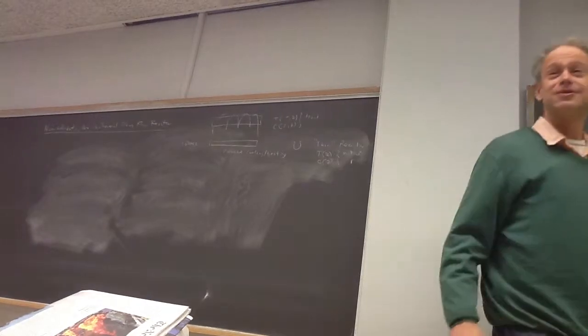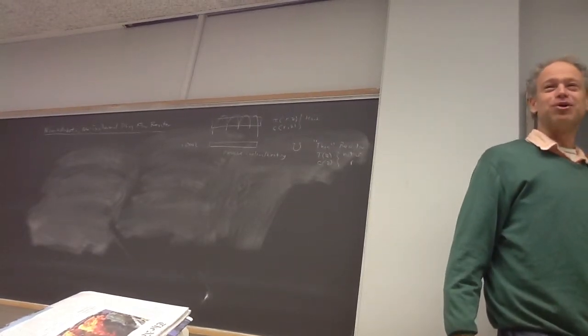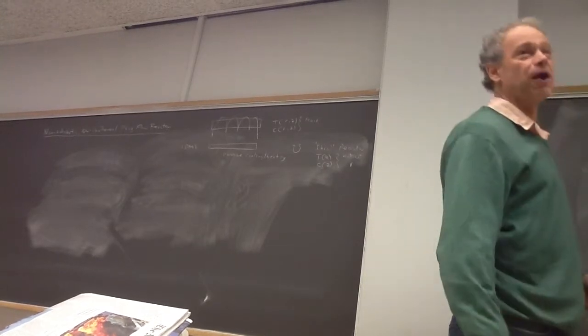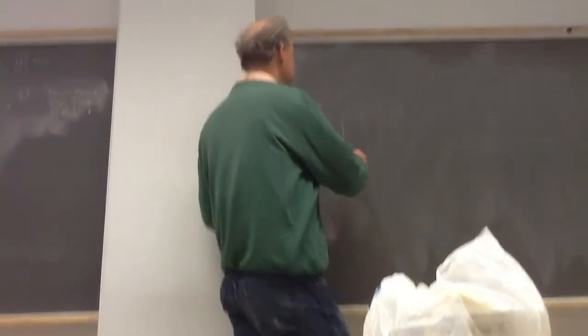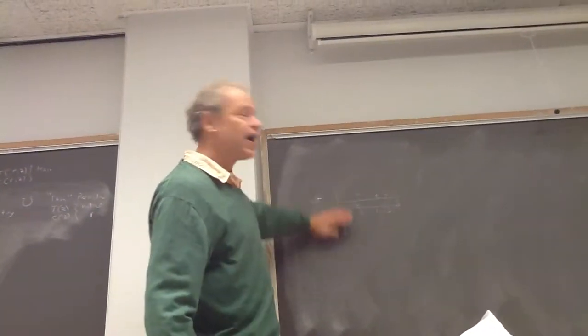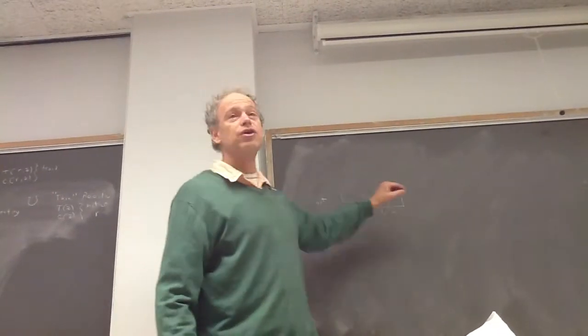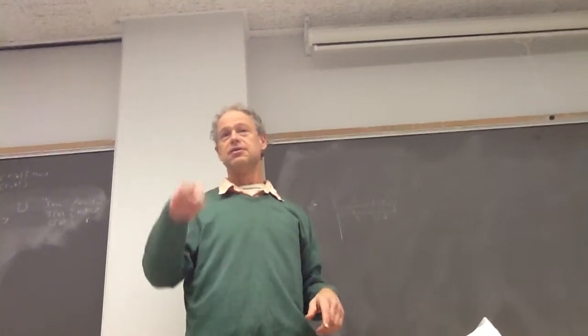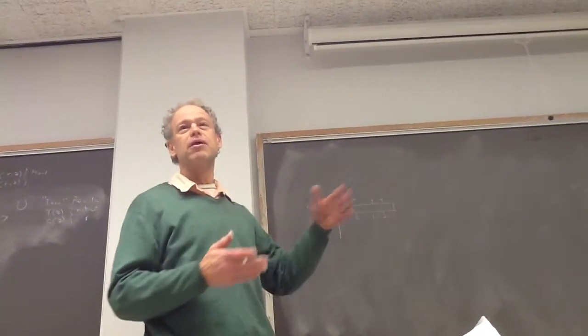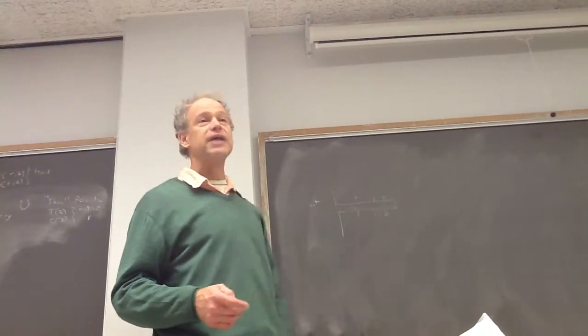What book did he use? This is in Bird, this problem. Anyway, in that problem, you look at the temperature. This is sort of like a radiator in your house. You've got the hot radiator, and if you look at the radiator, it typically has these fins, and that's to increase heat transfer. Now, of course, the fins usually come to a point, but if you ignore that, you assume it's rectangular.